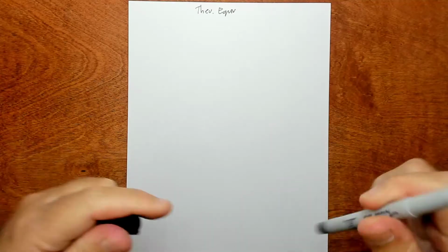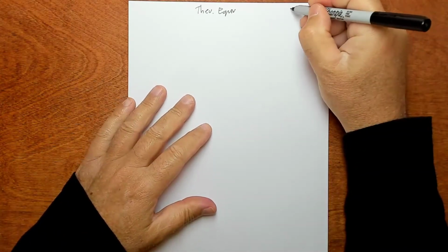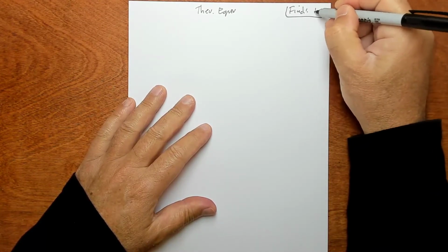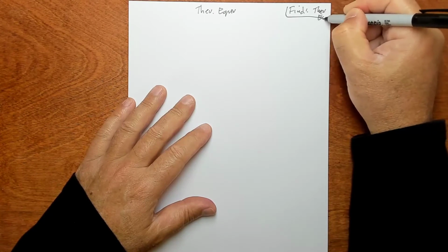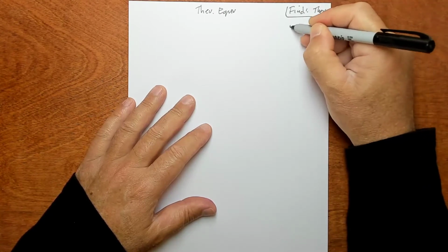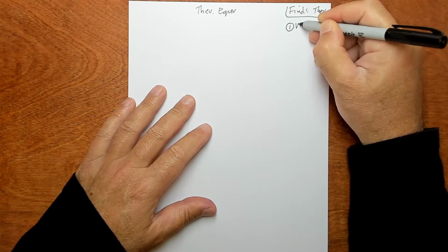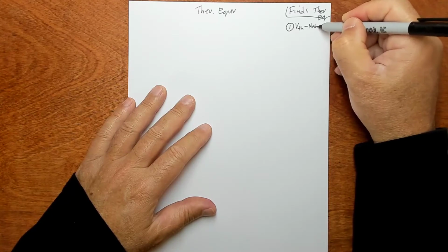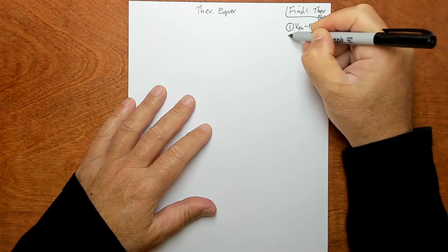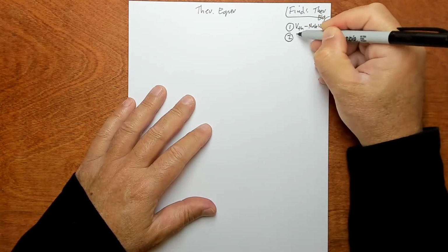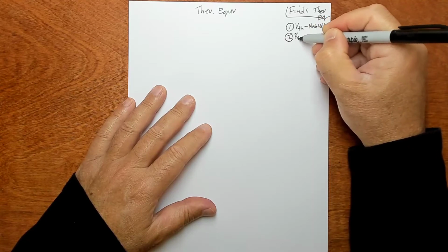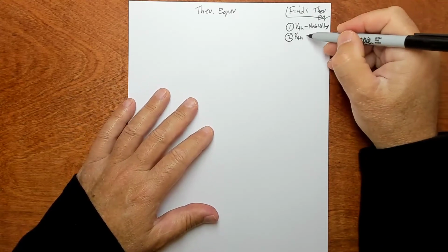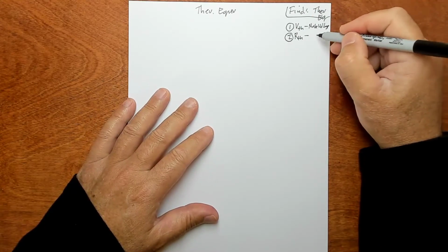Welcome back. Let's do another Thevenin equivalent. And this time we're going to do some different methodology here. So there's still two steps to this. One, you're going to find V sub Thevenin, and here we're going to use node voltage. But the second process that you do for these problems is you solve for R sub Thevenin as a kind of a separate problem. And here we're going to use the test source method.